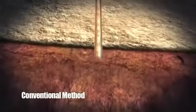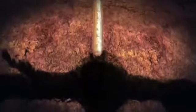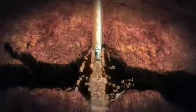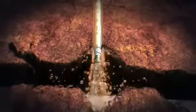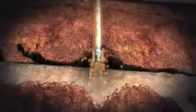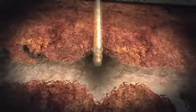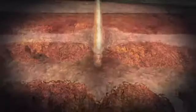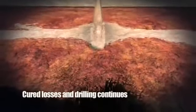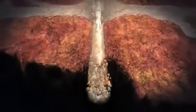Here's the typical scenario encountered with conventional drilling. While drilling ahead, a zone of low pressure is encountered. Pressure exerted by the drilling mud is higher than the formation pressure, and it begins to enter existing fractures and vugs. The driller's first response is to slow the circulation rate and add lost circulation material. If that fails, mud weight is reduced in an effort to match the formation pressure. If this mitigation is successful, drilling continues until a second set of fractures is encountered.